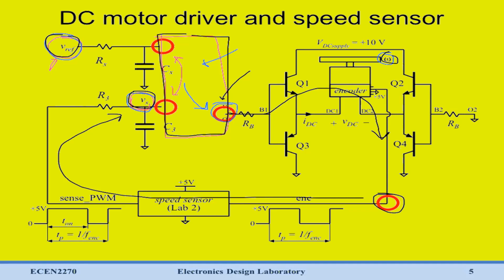We'll model our motor driver and our motor to get a relation between VO and omega. We'll model our speed sensor to get a relation between omega and Vs. And then we'll generate a controller which will take Vref as an input and generate a necessary VO. So first of all, let's take a look at this speed sensor portion, which takes omega and generates Vs.